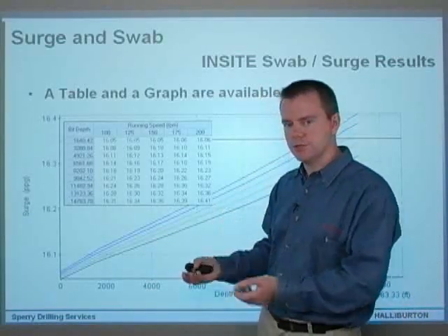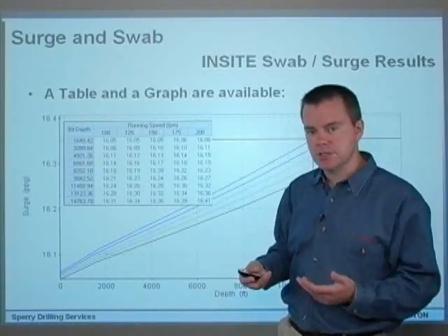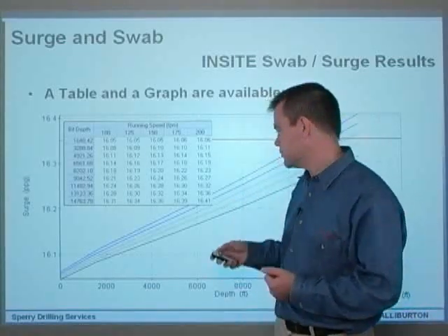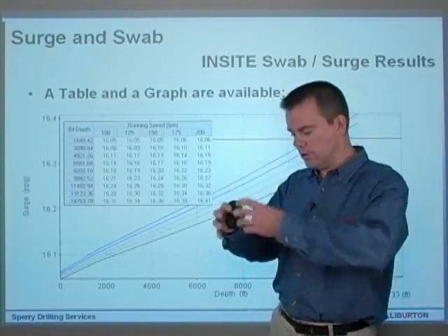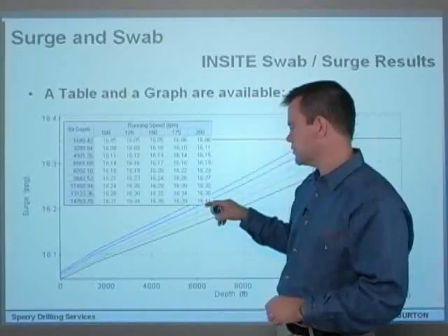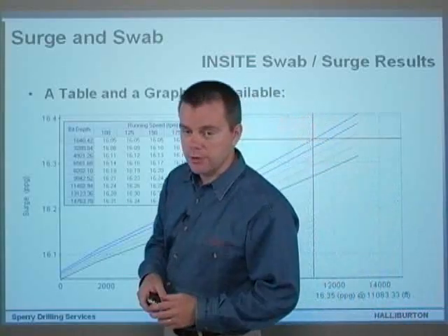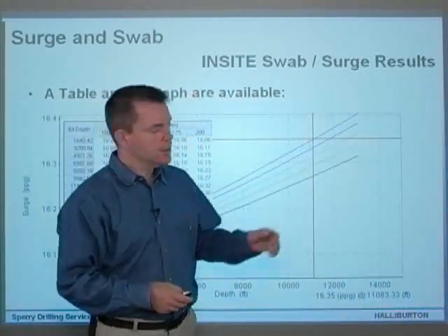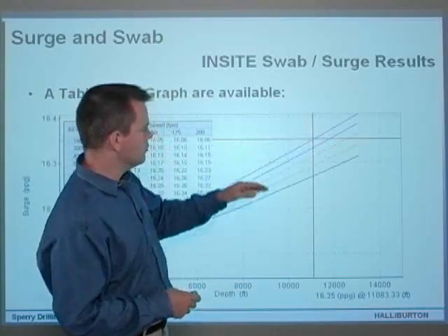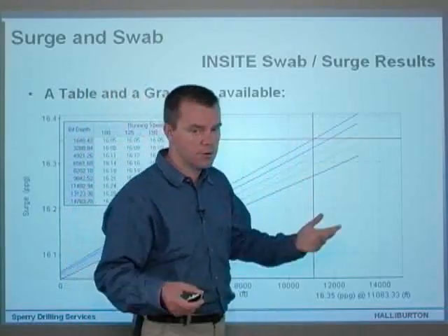So once all the pipe's in there and you're running at 200 feet per minute, that would be approximately a stand per 30 seconds, which isn't too unreasonable. A lot of people do run at that speed or faster sometimes. But when you're down near the bottom of the hole and you've got mud flowing past that entire annular section, it's quite significant. You've got 0.4 pound per gallon. On an HPHT well, the fracture gradient could be about here somewhere, and running at one of these speeds could just pop you over that fracture gradient and give you total losses in some cases.